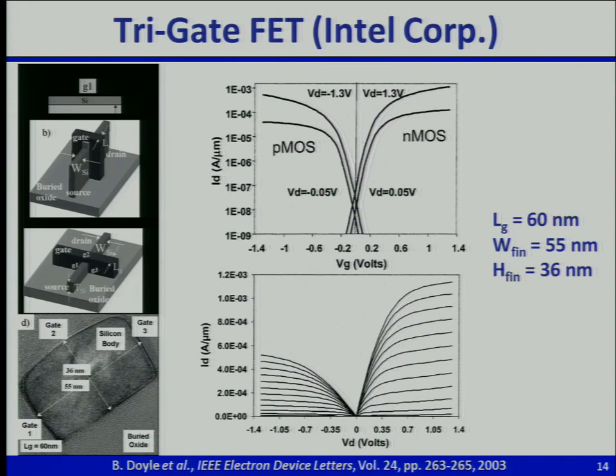They actually had the gate, well, of course, on the sidewalls, but also the gate on the top. And this silicon was actually rather thin, so it's kind of like in between a thin body transistor and a double gate transistor, right? So the fact that they made the silicon relatively thin as well, it's thinner than the thickness of that silicon fin. It's not really a fin anymore. But anyway, the height of that fin is less than the gate length.